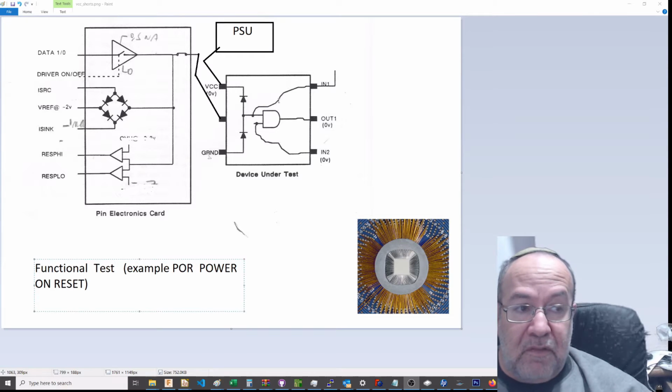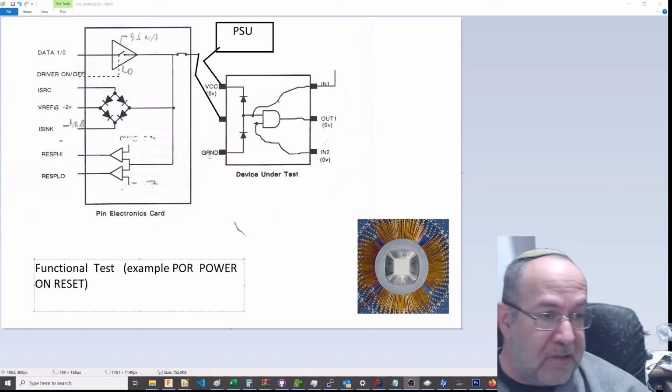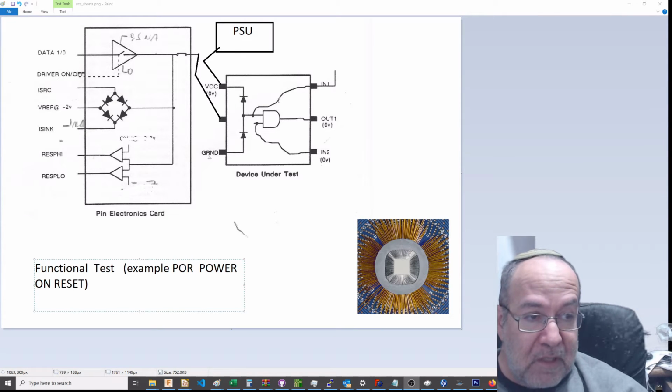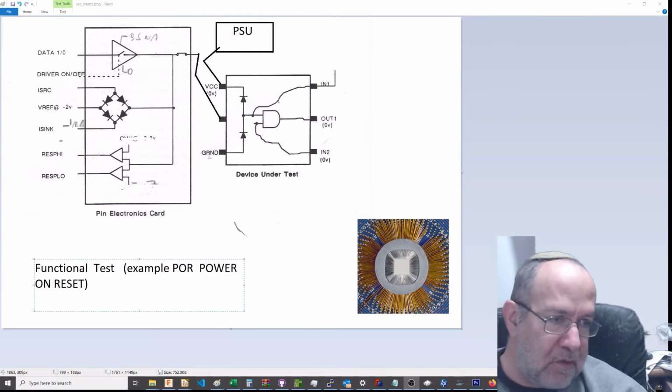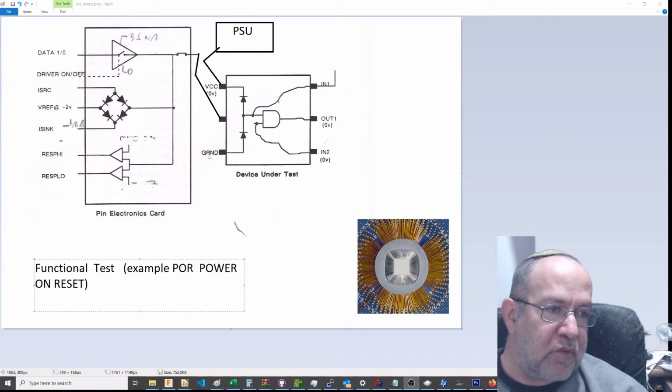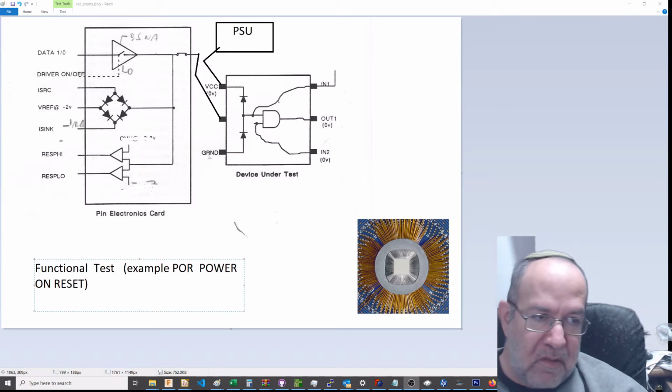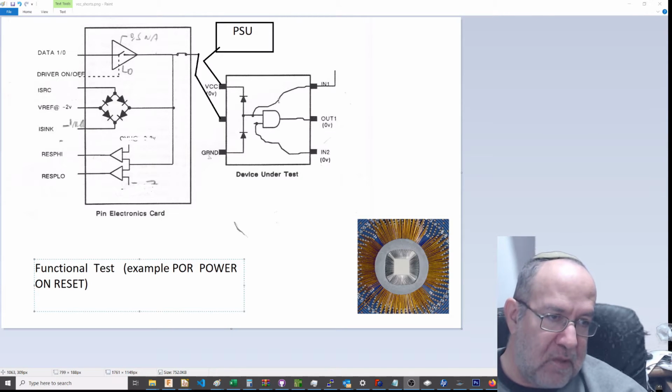Your current in power down mode. Your current in power down mode would be, at least for the generation where I worked on the chips, something which would have shown the quality of the silicon, how much leakage you have in the silicon.